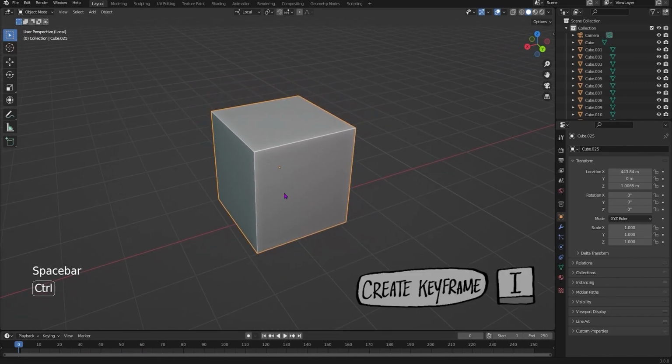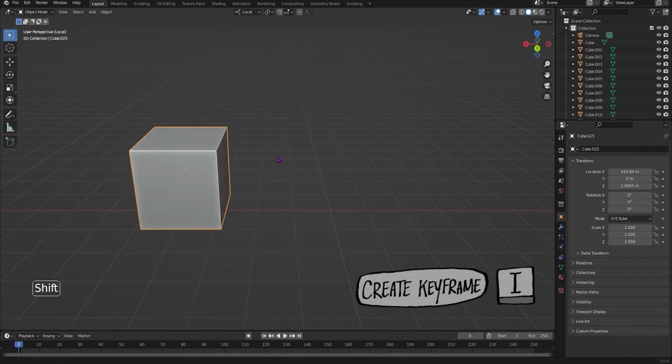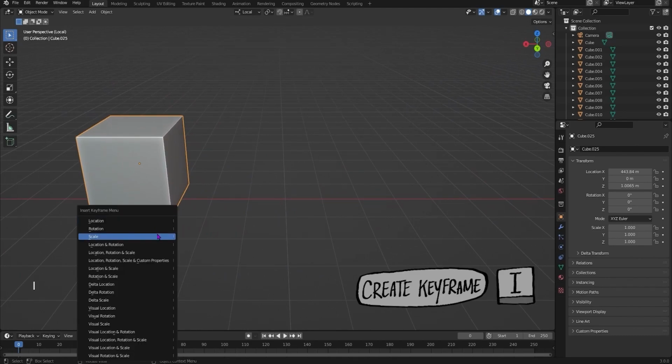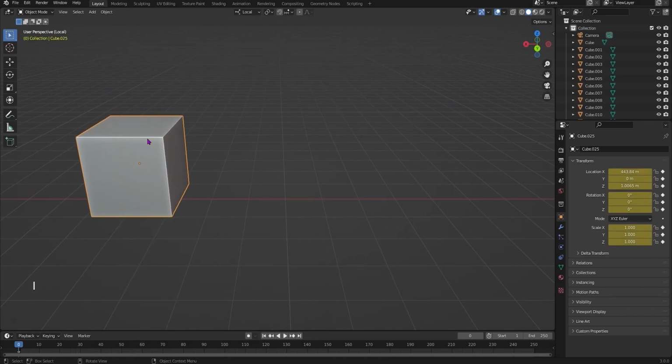And for this one, you're going to want to make sure that one of them is set to timeline. To create a keyframe for your animation, hit the I key. And when you create this keyframe, you're going to want to specify whether or not the object that you're animating is only going to be changed in its location, scale, rotation.